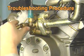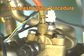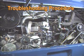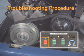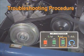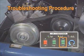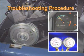Install the manifold gauge to the low pressure line service port and high pressure line service port. Start the engine and turn the air conditioner on and set the blower speed at high position. Run the air conditioner for over 5 minutes at 1100 RPMs and then read the scale of the manifold gauge.